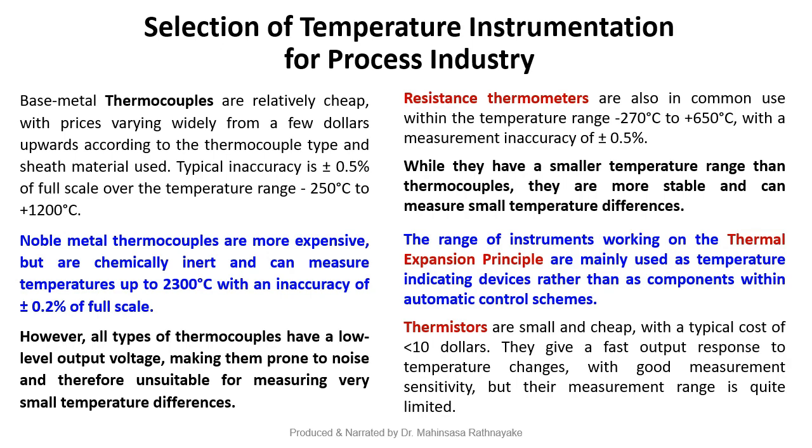So when we have to control the temperature of a certain process or unit operation, we can couple the measurement device with the control circuit. But when we use thermal expansion based thermometers like the liquid in glass thermometer, they are just indicators rather than controllable devices.